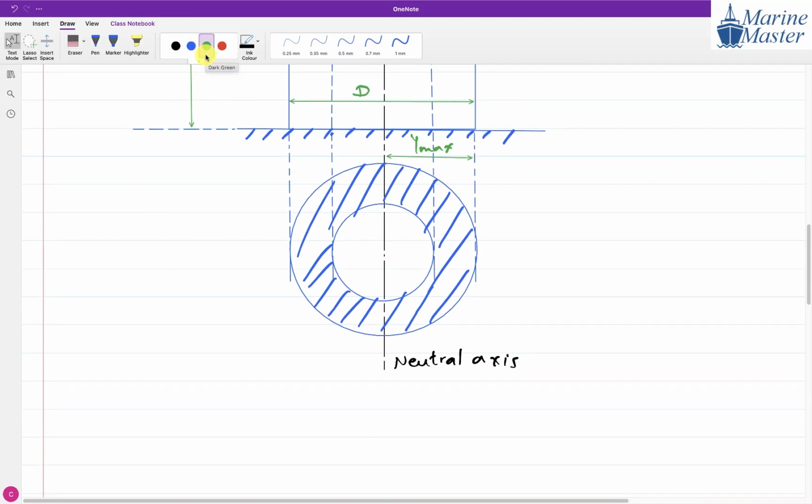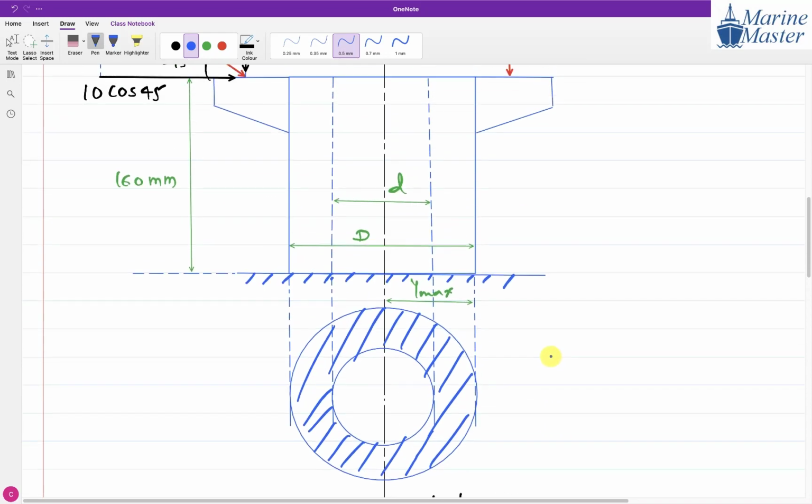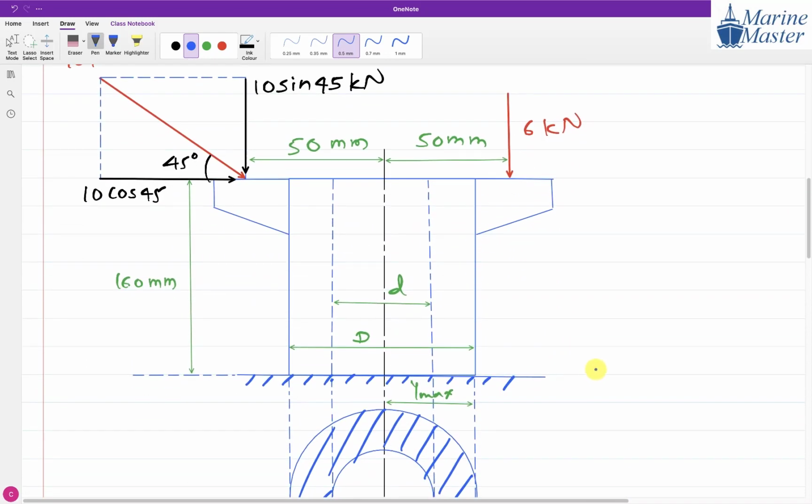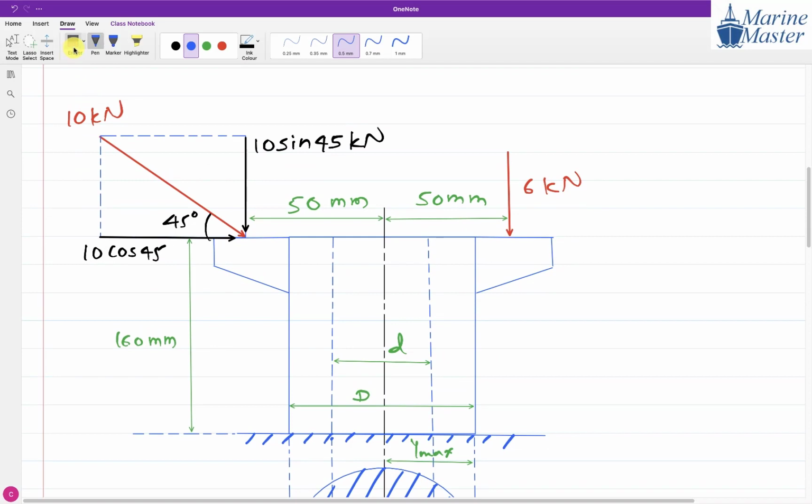See, two things are important here. Why are two things important, guys? Two things are always important here. One is to calculate the value of F, and another is to calculate the value of M. What are the two important things in case of eccentric loading? Force F, which creates direct stress, and the moment. So F and M.